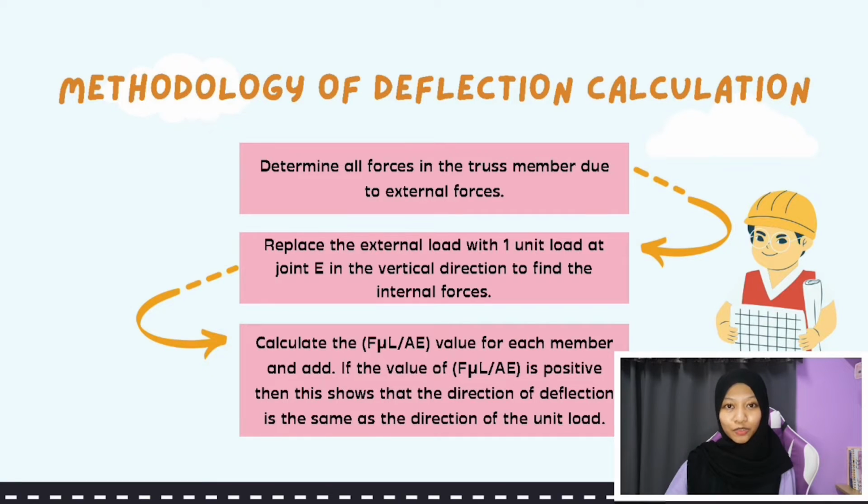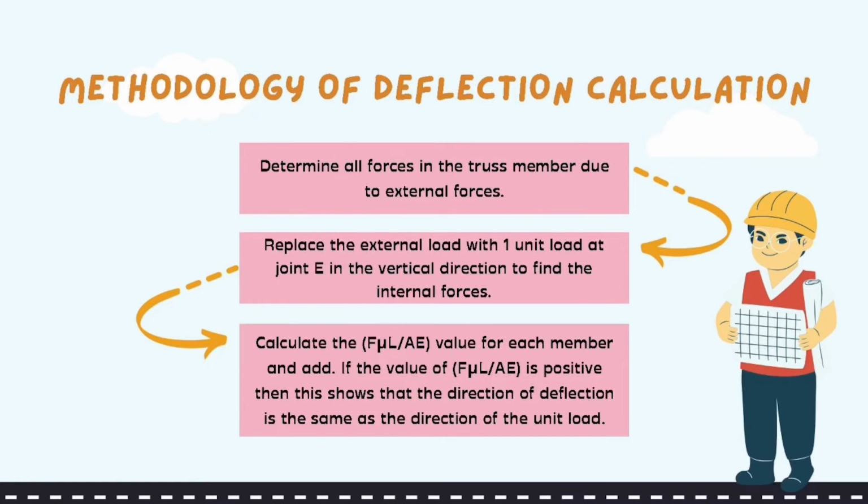For methodology of deflection calculation, the first step is to determine all forces in truss member due to external load. Then, replace the external load with 1 kN at joint E in the vertical direction. The final step is to find the deflection value.